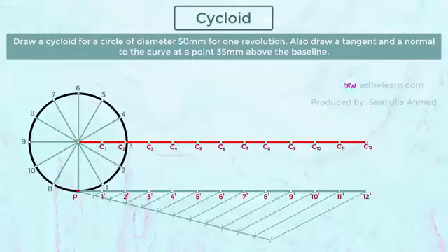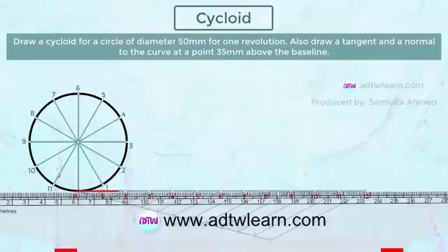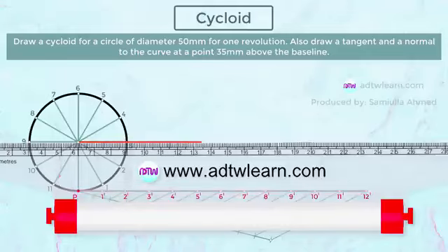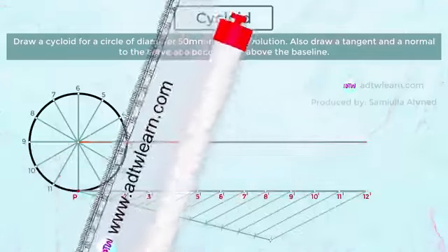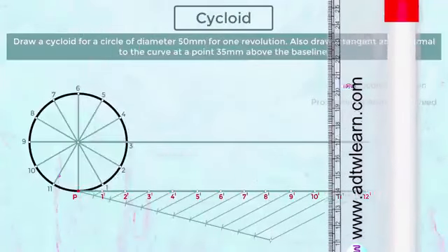To draw this line, take a roller scale, take this baseline as a reference, move the roller scale up to the center, and now draw a line. The length of this line will be equal to the baseline. And draw a vertical end line here.